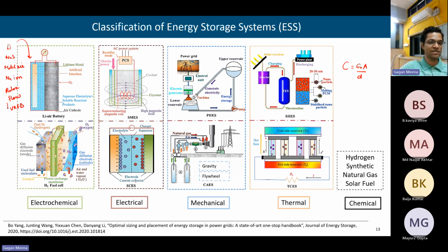These two are high power density devices. They cannot provide very long discharge durations. That's why they are used where we require very fast response, for example flash charging, as you have heard. We can use these supercapacitors there, and for primary frequency regulation services. Similarly for SMES also.